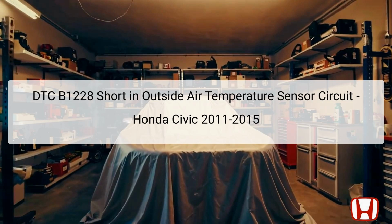This component sends temperature data to the climate control system, which adjusts cabin conditions based on outside temperatures. A short in this circuit can lead to incorrect temperature readings, adversely affecting climate control performance and overall driving comfort. Diagnosing DTC B1228 involves thorough checks of the related wiring and components to identify the source of the problem.